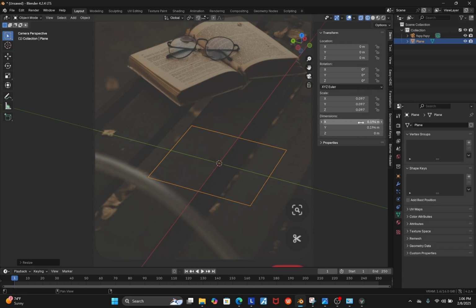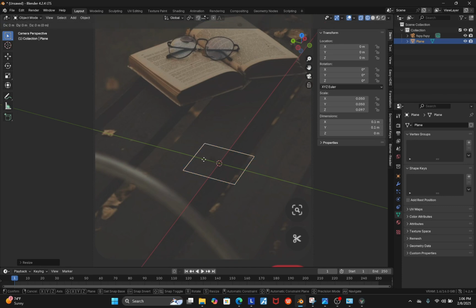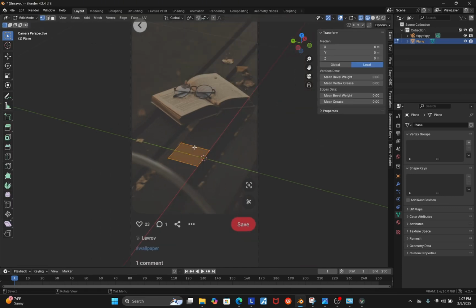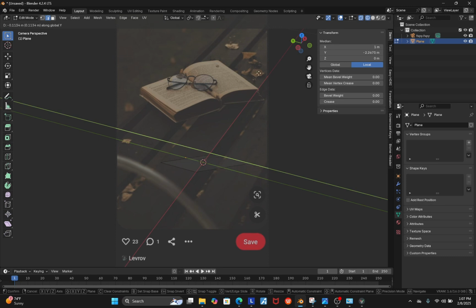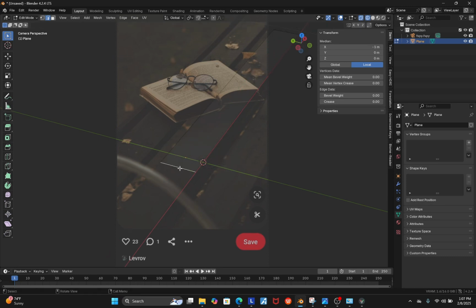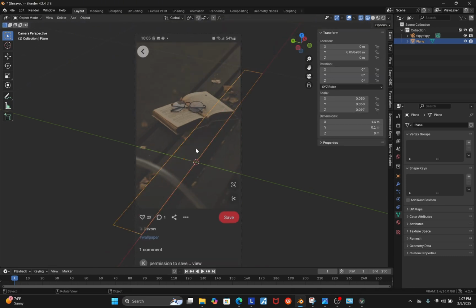As you can see, we have the dimensions. So what I'm going to do is give it 0.1, since we have made the bench 0.1. So if I press GY and move it, something like this, as you can see, we have got the perspective correctly. And I can go inside of the edit mode, press GX and move it like this. GX, as you can see.